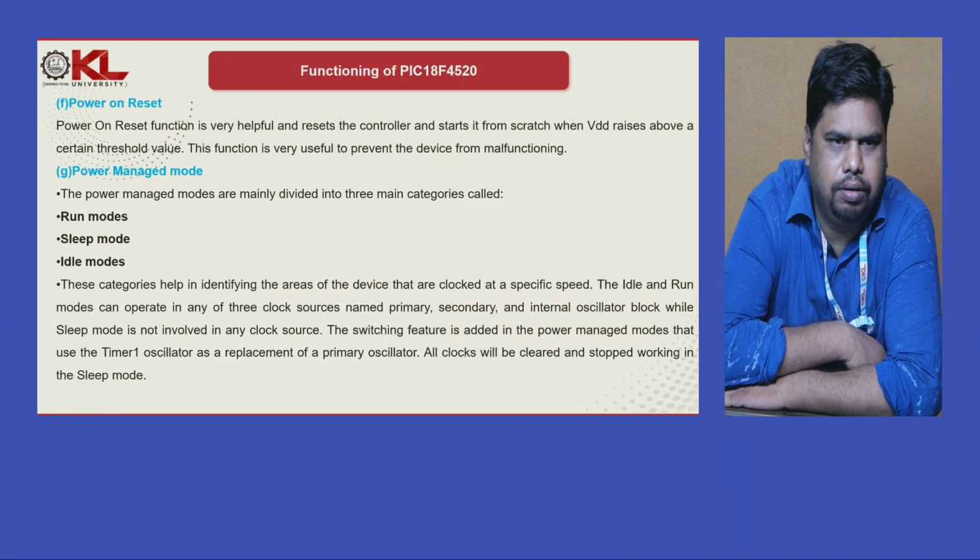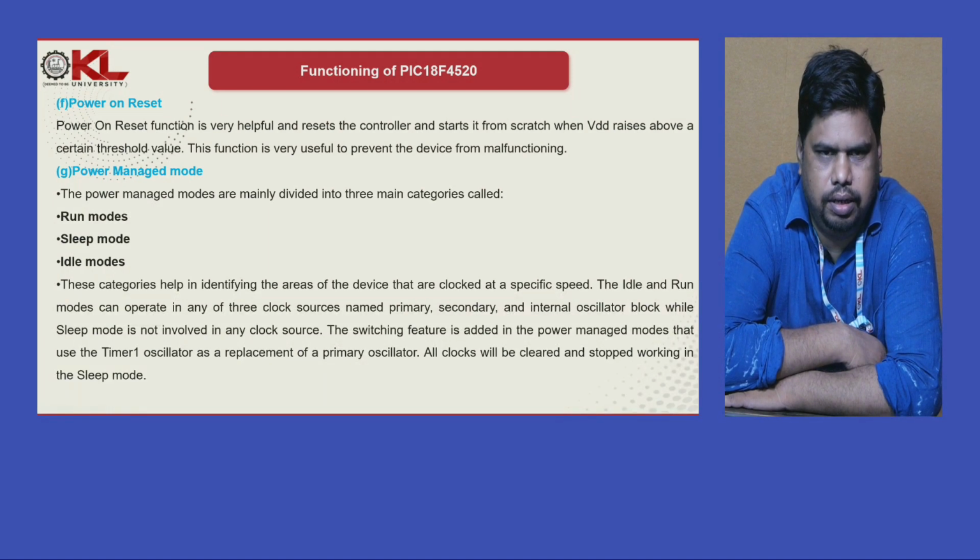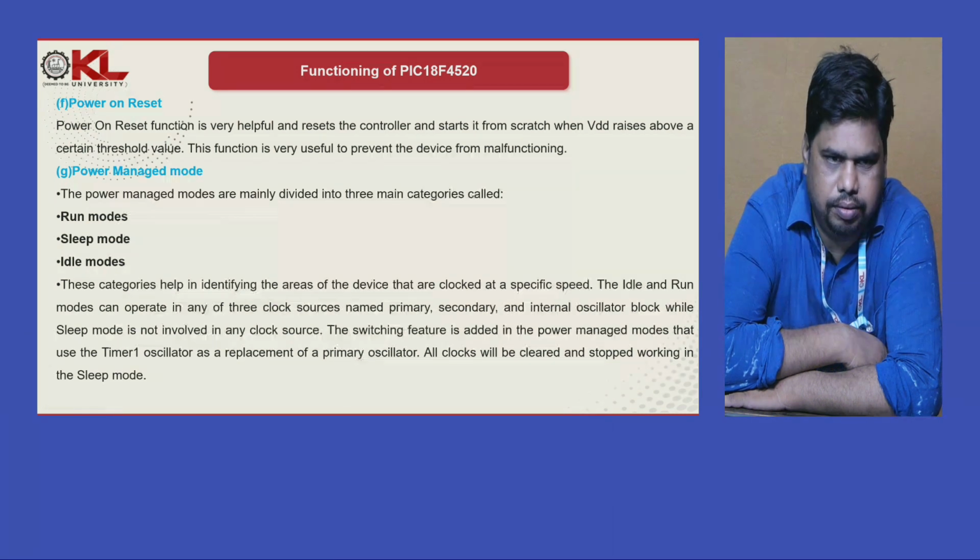Then the power on reset function is very helpful. It resets the controller and starts it from scratch when the VDD supply voltage rises above a certain threshold value. So this function is very useful to prevent the device from malfunctioning.